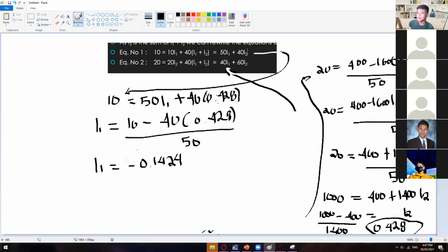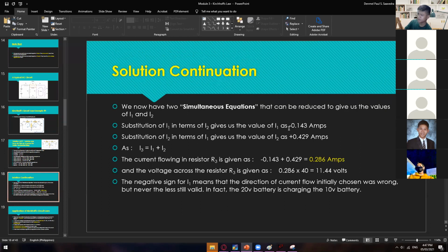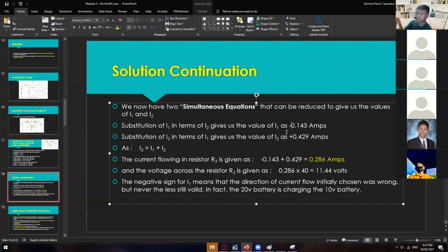So from here, as you guys can see, we have a negative sign, meaning the assumption of the flow of current is actually the opposite way. So I sub 1 is supposedly flowing counterclockwise, okay, not in the conventional way. So it's in the counterclockwise loop or direction, right? So again, if you guys have received a negative sign, just make that one positive. Then you will get a correct answer.